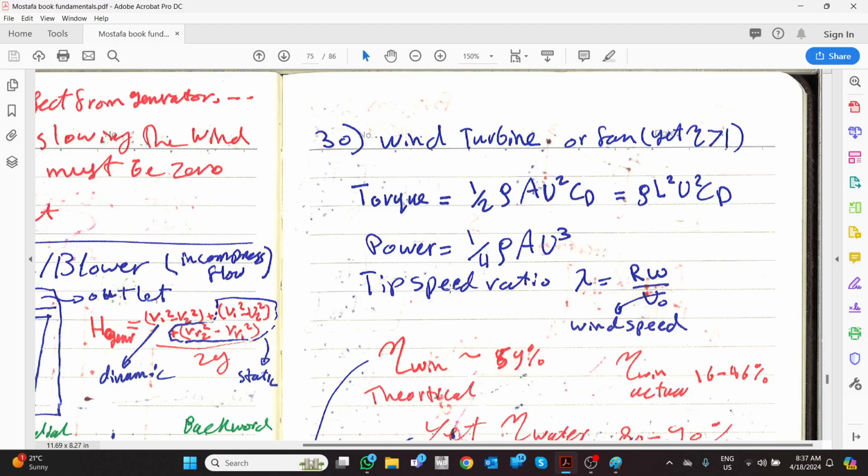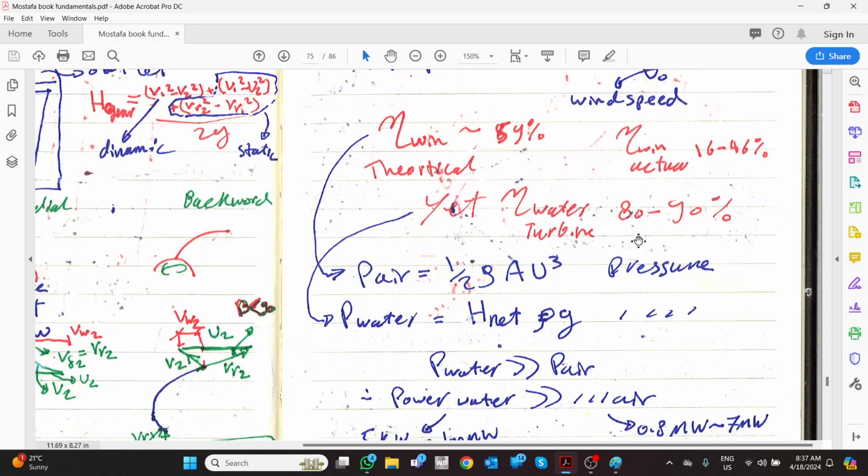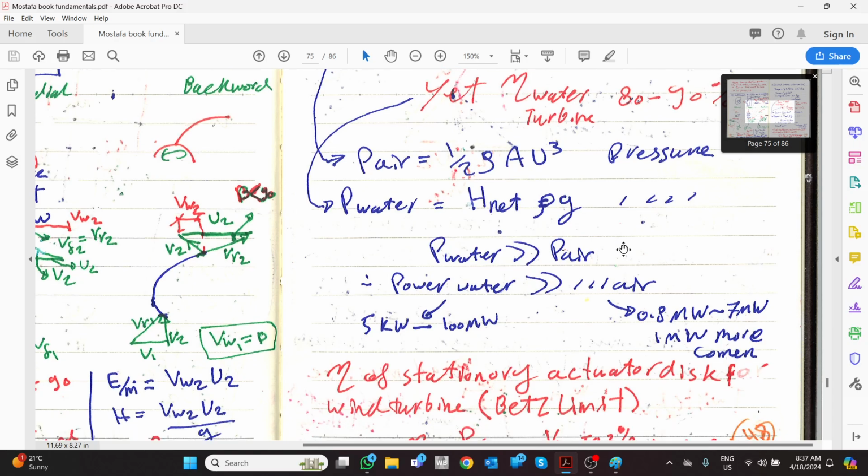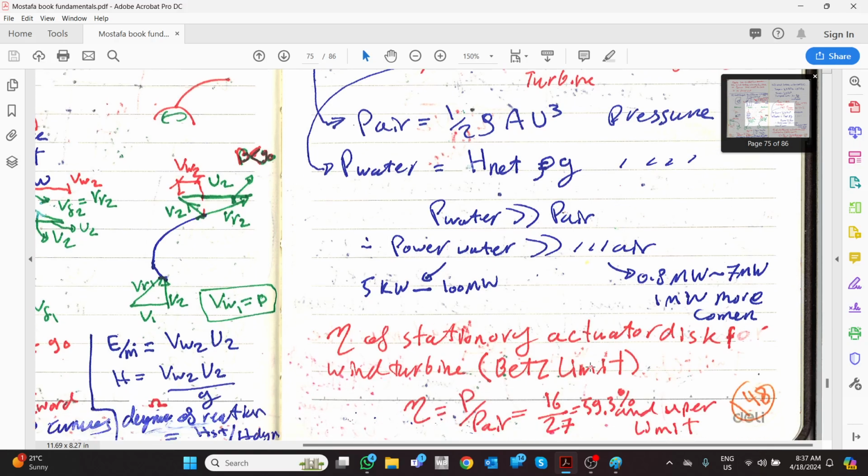Yet we know that not the full kinetic energy is going to be converted, as the exit velocity will never be 0. So theoretically there is an efficiency of the turbine which is less than 1. And it's a similar case for the fan: not efficiency, but the power input factor of the fan should be bigger than 1. It is impossible to reach 0 velocity out, which has been written here.